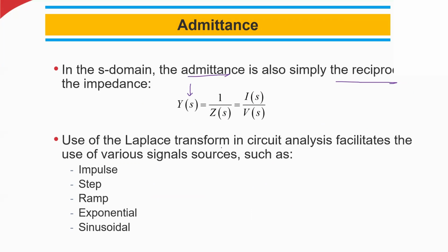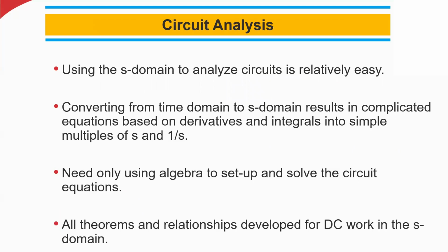Use of the Laplace transform in circuit analysis facilitates the use of various signal sources such as impulse response, step response or unit response, ramp response, exponential, sinusoidal. Whatever the signal sources, we can represent everything in Laplace domain. Circuit analysis using the S domain is relatively easy.